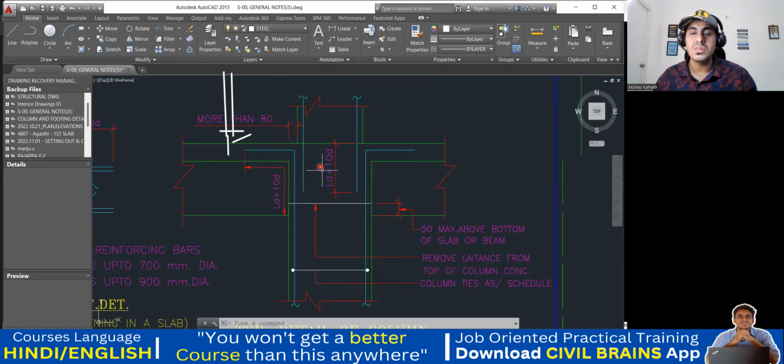This is for fresh concrete; for that it is valid. But when your concrete is already set, and after 1 year you're drilling, you cannot drill 720 mm. So 100 mm, 150 mm is sufficient, and then you insert that chemical gel. Through that, it will have a good bond, nitro bond you can use. This is when you want to give new reinforcement in an ongoing process. That means you finished the third floor, and in the third floor you felt you need to add another 2 rebar. In that case, you can start with the additional reinforcement.